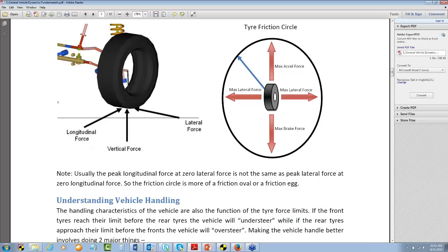Your vehicle is sometimes accelerating in the longitudinal direction, or it is accelerating or decelerating in the lateral direction. Now if you add up both these components, then you have the total acceleration or the total force acting on the contact patches. Now this thing has to be smaller than or equal to mu g, which is the total available contact patch,